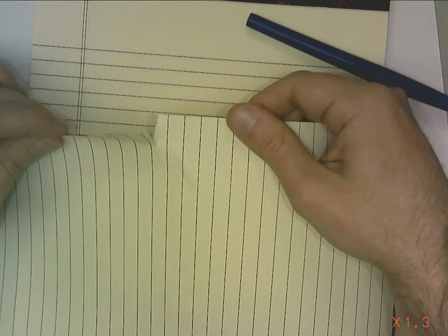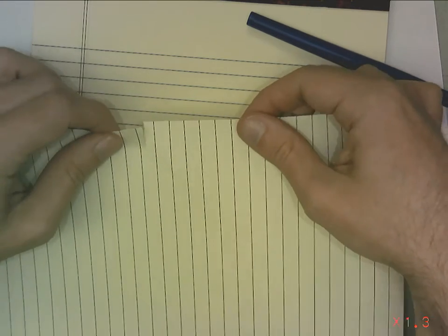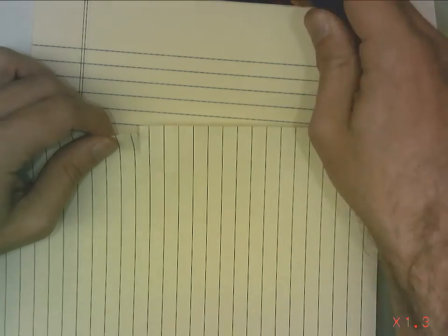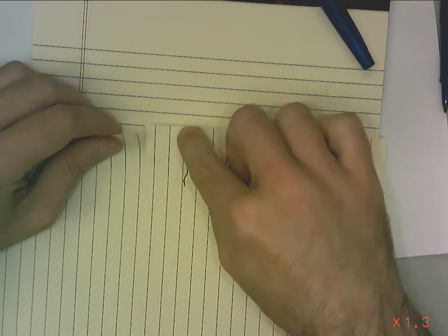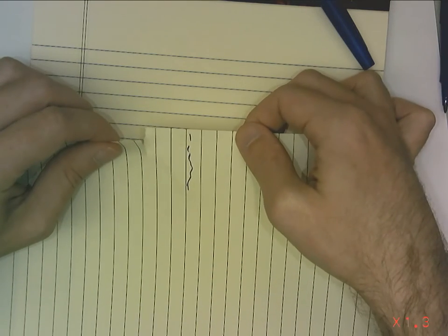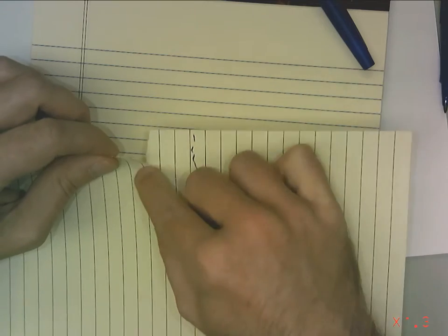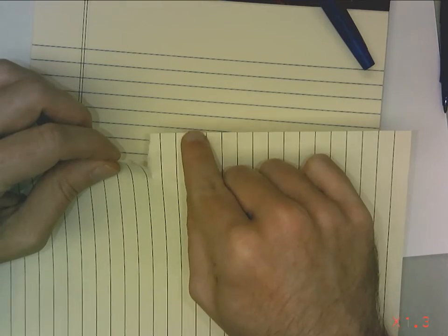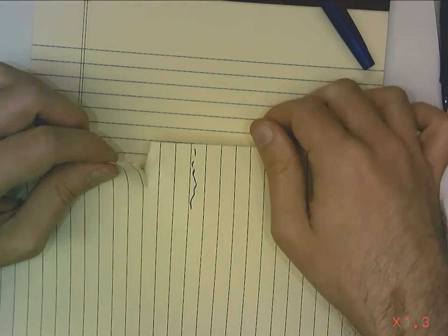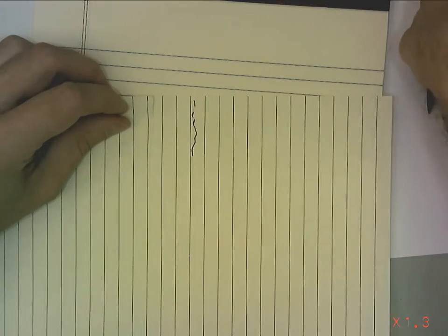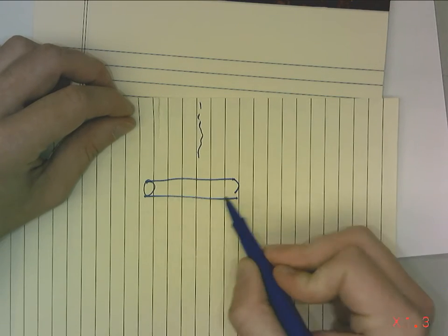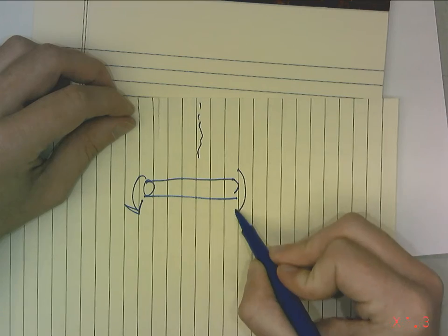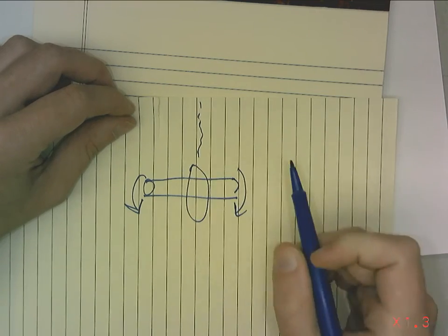If I've already got a tear in it, well, gosh, let's come over here. My highest torsion or bending should be in the middle between my fingers now. But it comes over here. Math says this should be the highest stress because it's in the middle, right? So if I've got a shaft simulated by a piece of paper and I'm putting a bending moment on it, my highest stress should be in the middle.